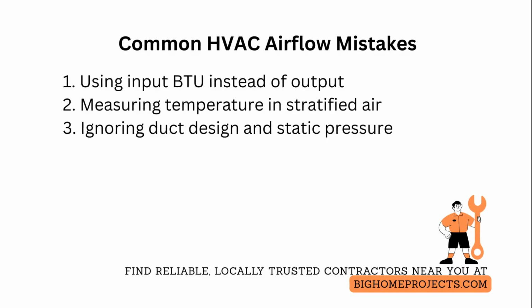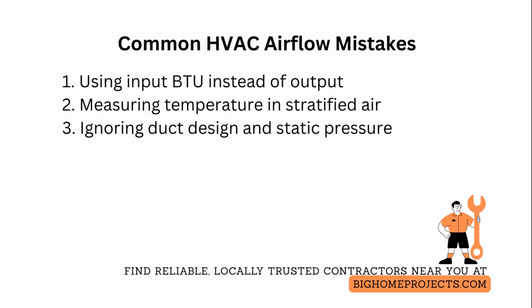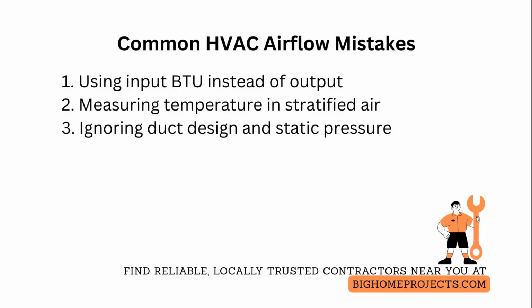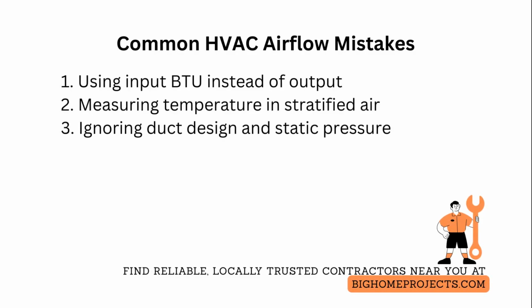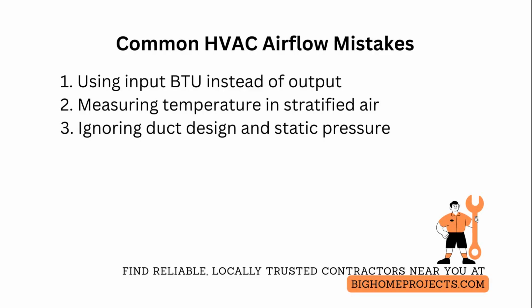Another common issue in airflow measurement is taking temperature rise too close to the heat exchanger or directly downstream of the evaporator coil, where air is stratified and sensors read hot or cold streaks. Relocate probes to well-mixed locations and use 2 probes averaged if space allows for more accurate airflow testing.